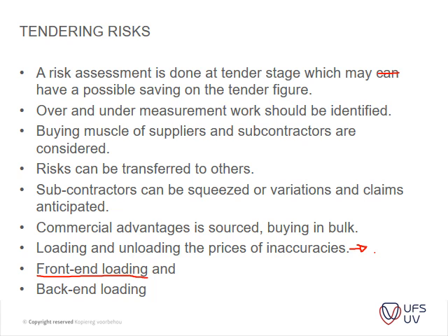It might happen that when you remeasure your work on site, your excavations might be much less than you anticipated, in which instance you will lose on your contract, because now your back end items will not have the necessary rates or bulk of finance to carry you through the project. So please note that this is a very risky item, and the QSs usually pick it up when you do your leveling of your rates before you get appointed.